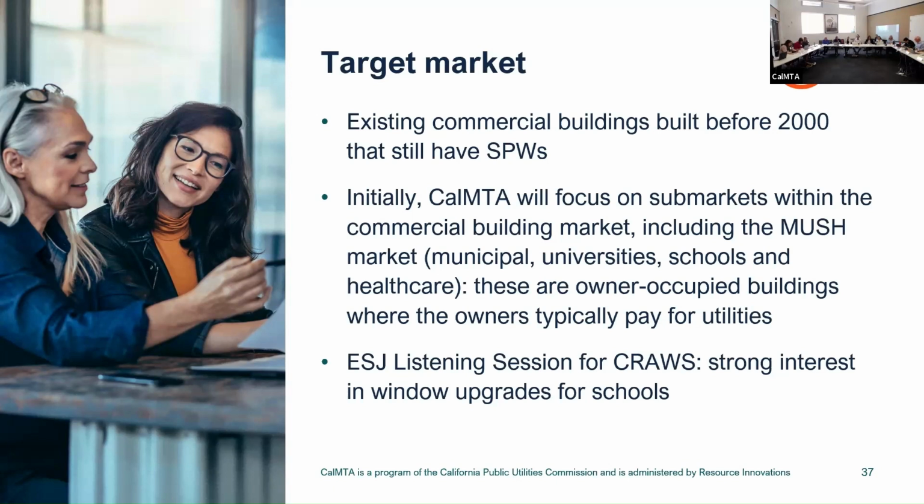Fascinating presentation at Getting to Zero recently about a project in schools where they're trying to determine the threshold for thermal comfort, because it's so challenging to add air conditioning from a budgetary perspective. They were using ASHRAE 55 in a very statistical, methodical way to determine the limit of thermal comfort in buildings. They're looking at defining thermal comfort as 88 degrees and below.